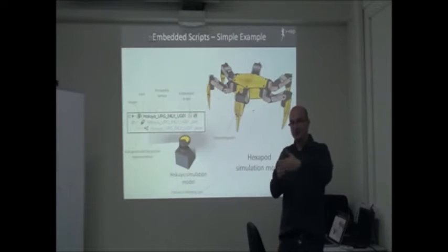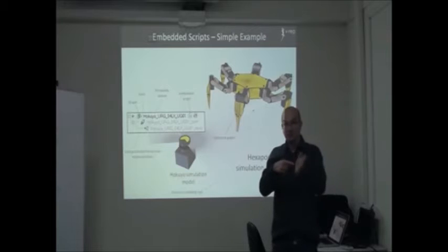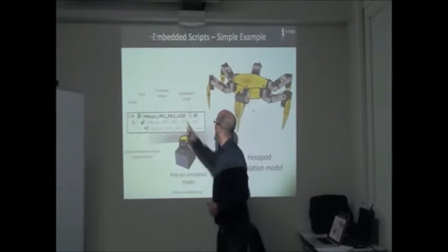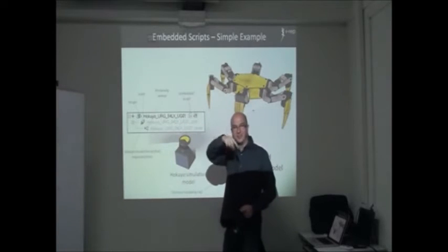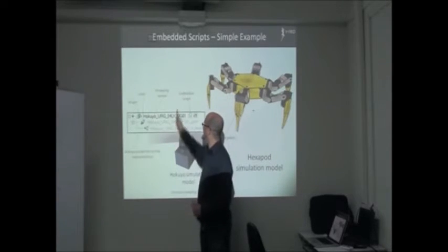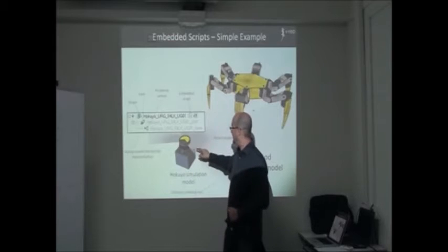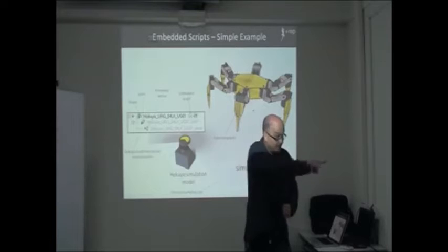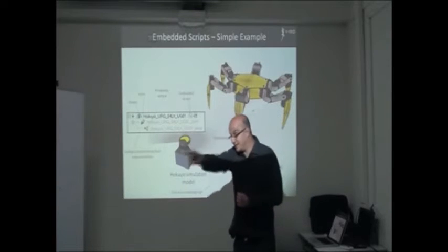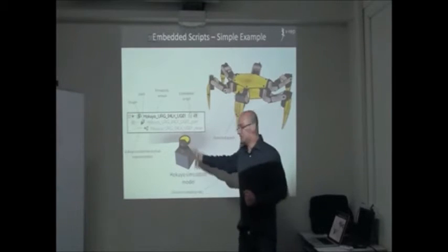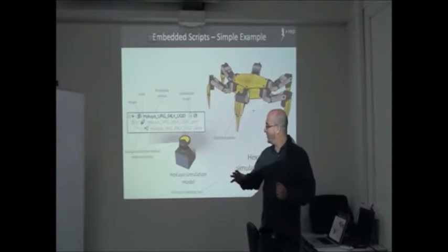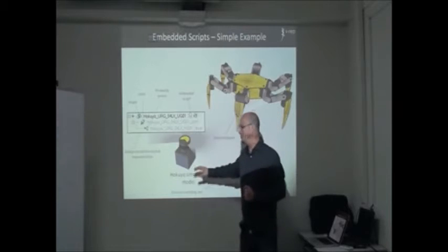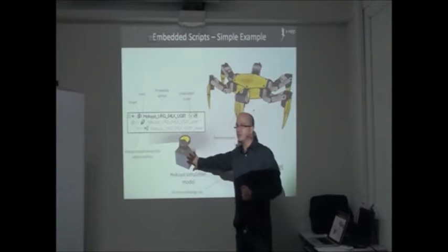And then you put a mirror, a rotating mirror. The rotating mirror will diffract the laser to different orientations, like this. So with one laser and one rotating mirror, you can have plenty of measurements in the plane. So I'm showing the laser here, at you, sorry for your eyes. It's eyesight safe, don't worry, especially in the simulation. And I'm measuring distances on the plane. So it's a pretty expensive sensor, but it's very useful for a robot.